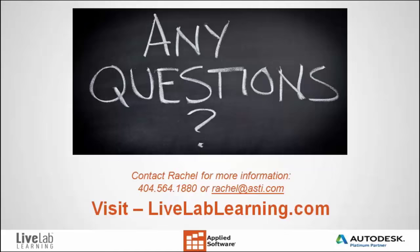Okay. Next question is from Darren Young. When the auto conduit routing takes place, can it detect architecture, structure, or other piping HVAC systems to avoid clashes? Not automatically. And basically, I'm going to repeat the same answer. I typically will do what I'll call a preliminary or conceptual routing quickly in CARS and then bring it into a Navisworks environment to look at those clashes, and we can very easily modify the raceways, whether they were auto-routed or whether they were manually routed. The raceways can easily be modified after the fact.